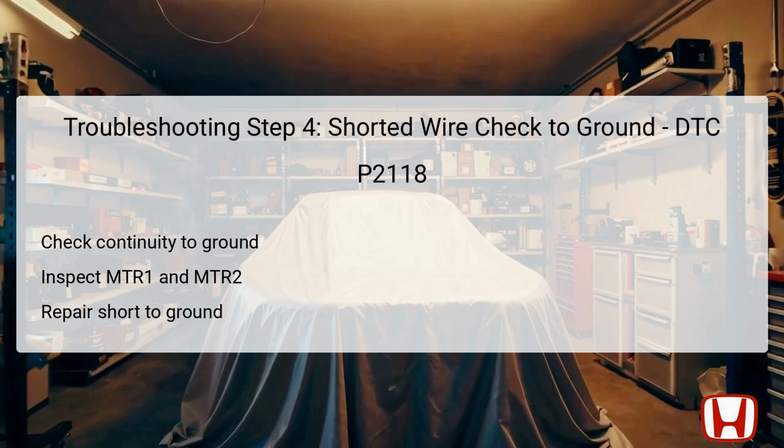and MTR2 wires. Ensure the ignition is turned off and the necessary connectors are disconnected as in previous steps. Measure continuity from the test points of the MTR1 and MTR2 wires to the body ground. If continuity exists, this indicates that the MTR1 or MTR2 wire is shorted to ground, which can severely disrupt the throttle actuator's performance. If you do find such a short, immediate repairs will be necessary to rectify this condition. Once the repair is complete, you must re-verify that everything functions as it should.